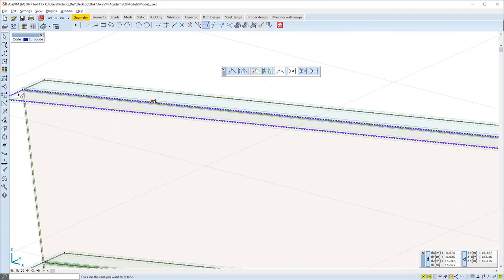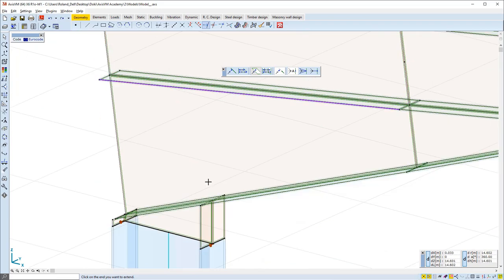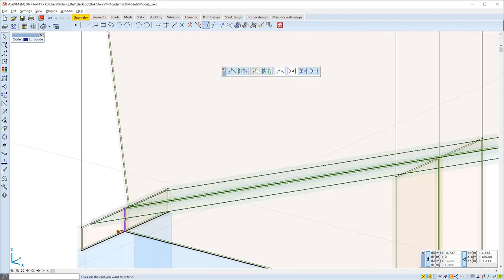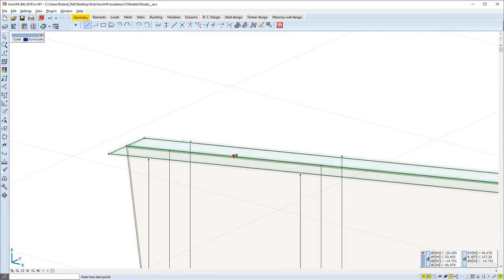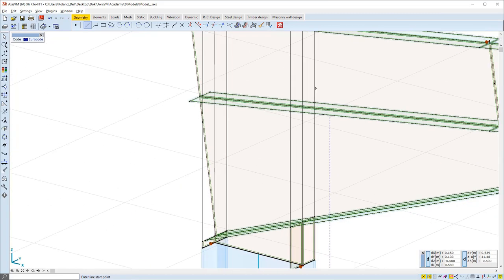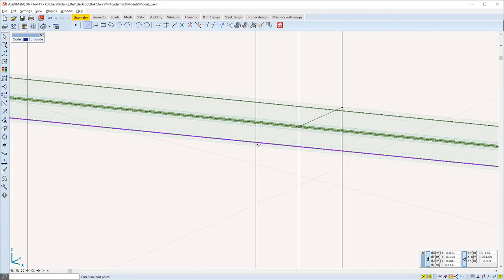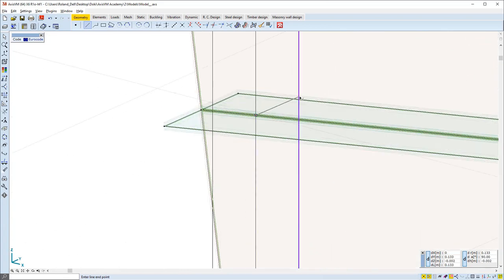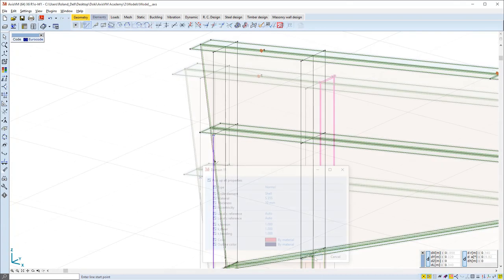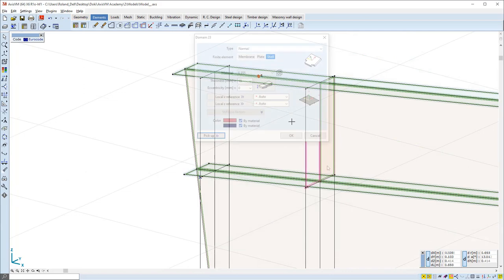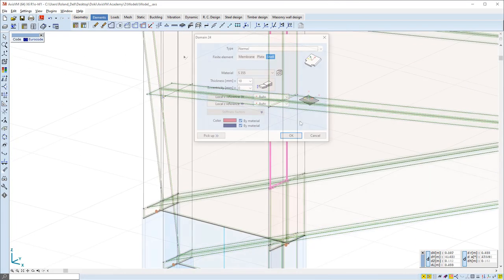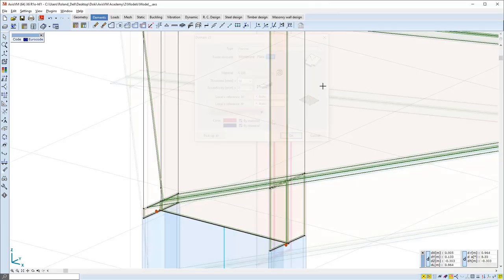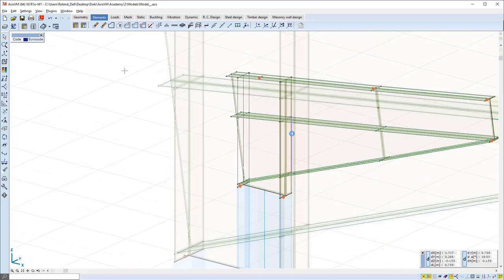After selecting the beam's upper flange as the boundary plane, each line of the column's inner and outer flange needs to be clicked to be extended. Plate contours are completed using simple line elements where it connects to the beam's flanges. And so each rectangle can be turned into a steel domain, acting as the flange of the column one by one.